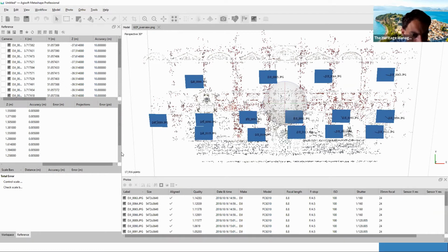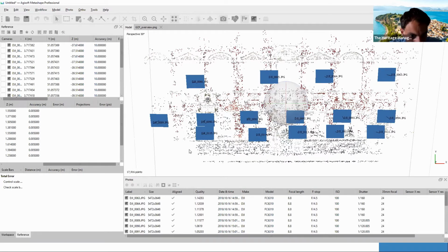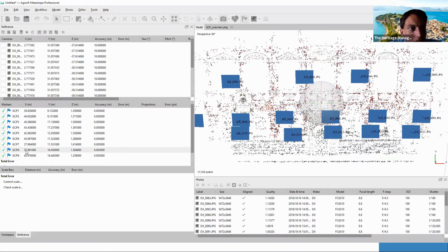And the result of that, let me enlarge this screen a little bit. Voila. The result of that is that under my cameras, for which I have disabled the coordinates, I also see the list of my 9 ground control points with the X coordinate, the Y coordinate, Z coordinate, expressed in meters. So make sure that you don't see any non-metric coordinates over here. I have an accuracy field. This accuracy field is used as some kind of a weight for the triangulation. By default, it's 5 millimeters. We will not discuss that too much.